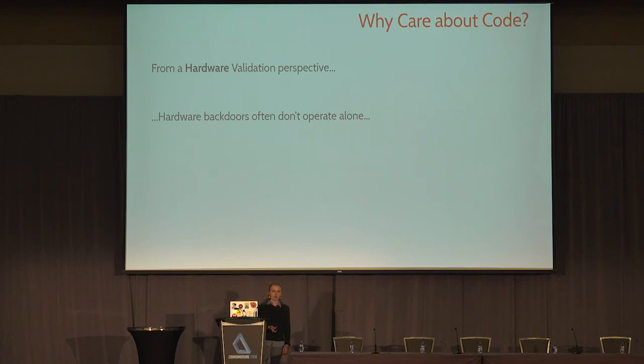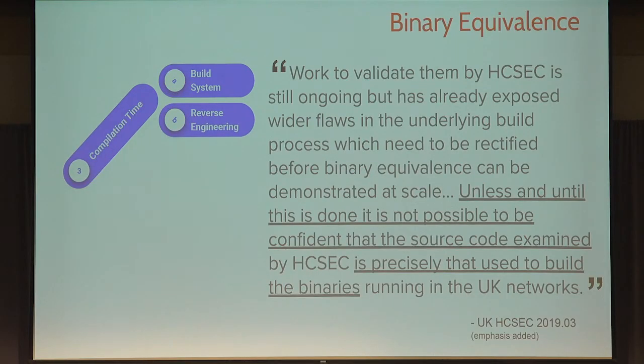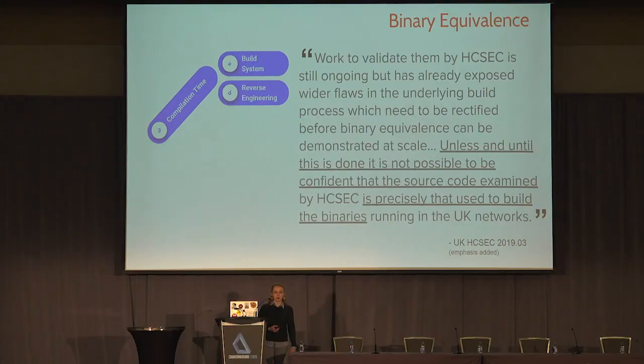All right, so this is one thing I mentioned earlier, but one thing to reiterate is all hardware implants don't operate alone. They probably can. However, if you actually want a successful, useful tool that's implanted onto the board, you'll actually have to have a software component here. And so what do you do with that, right? So how do you check that the software isn't actually abusing or using a misprint or an incorrectness in that board? And so, you can check your code at compile time, look at the build system, reverse engineer the firmware that you pull from the board, which is what we did with SuperMicro.